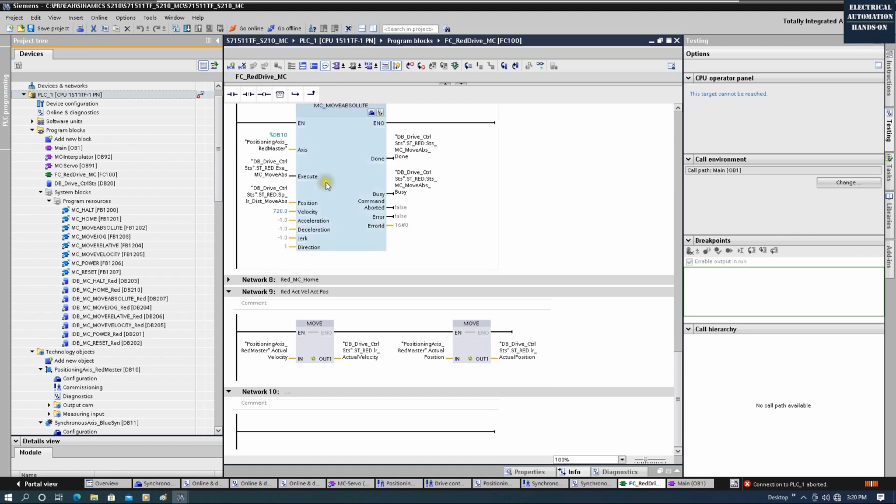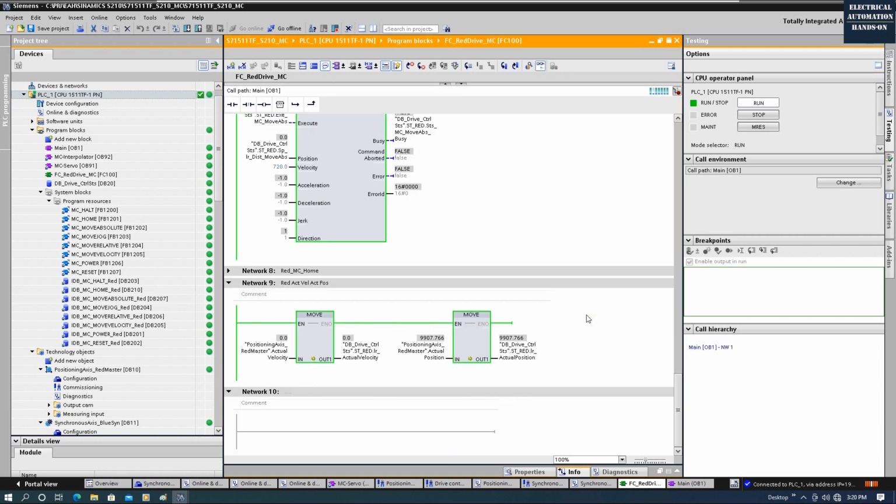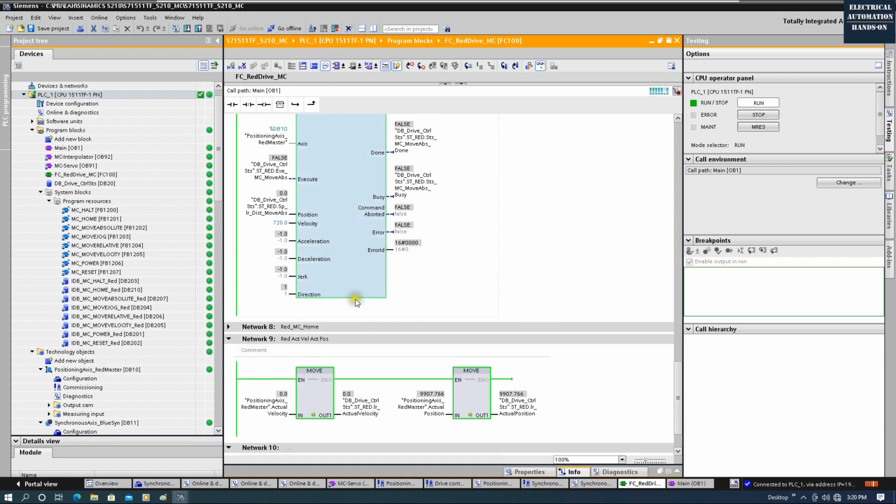Okay, the system powers up. Then let's go online and click this monitor. Click this monitor. Okay, we will see it basically moved 93 degrees. Because I moved backward, it goes slightly lower than the 10,000. That means during the power down, if we move this tool, this absolute encoder can record this position. Okay, this is the way to operate the absolute encoder.